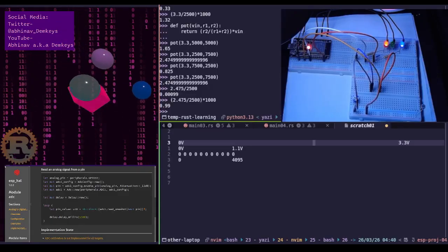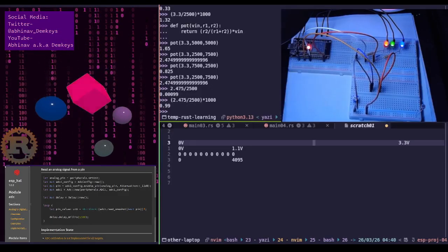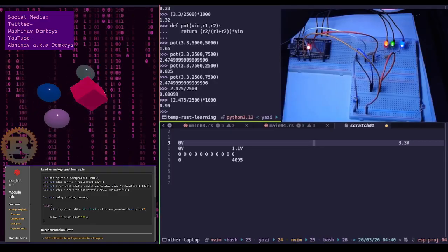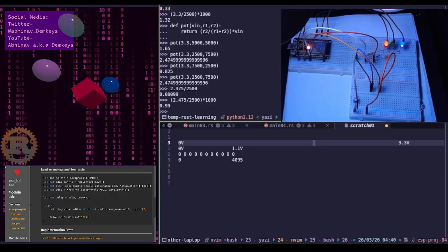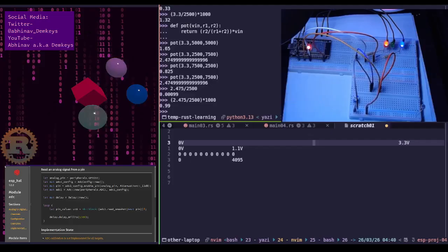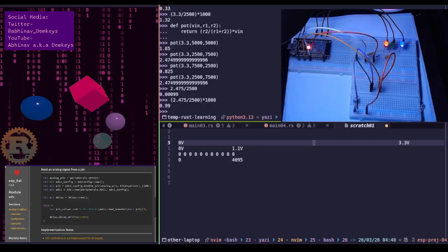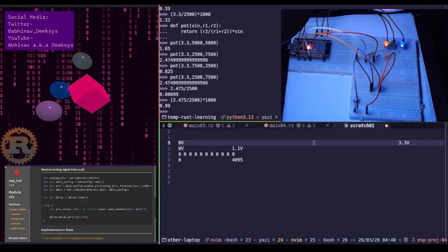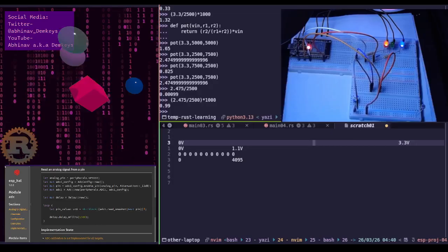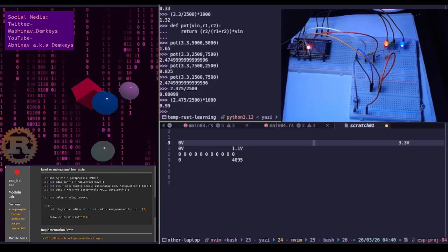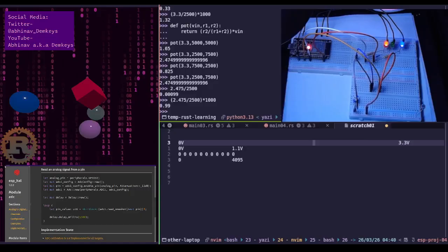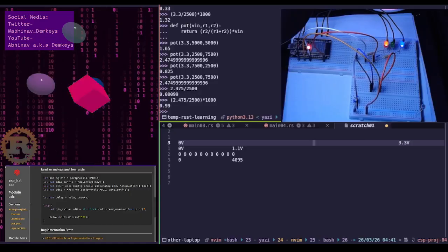The most important rule for the ESP32 GPIO pins is that the voltage should never exceed VDD plus 0.3 volts. If your ESP32 is running on 3.3 volts, the maximum safe voltage is about, oh, that's what VDD is. Whatever the microcontroller is officially running at, or whatever its max voltage is.